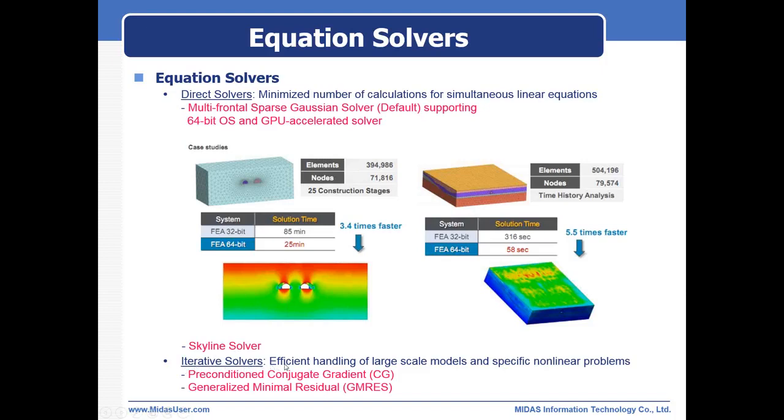Iterative solvers are very much helpful for large scale models and some specific nonlinear problems, whereas direct solvers are generally used for simultaneous linear equations. Amongst these, the multifrontal solver is the most commonly used one. For this, we support 64-bit operating system with GPU acceleration, which enhances the analysis capabilities by 3 to 6 times compared to 32-bit operating system.